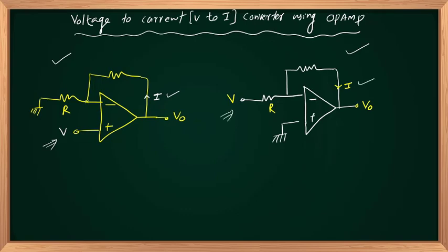In your non-inverting amplifier, the current I is supplied by the op-amp and that current is equal to the current flowing through the input resistance. Virtually, this will be at V potential, so (V minus 0) by R, that is V upon R. Current flows through R. The same current has to flow through the resistance connected in between output and inverting terminals of the op-amp.